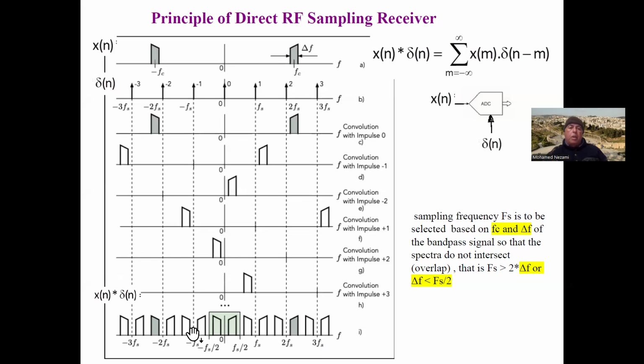So therefore, you can come in your digital domain here and say, I want to pick any of these that are appropriate for myself, either using a filter, or using a decimation process, or using frequency rotation, a digital down converter. So you can utilize a digital down converter to bring this one right to here. The whole series will shift down also, and then filter out just that one alone.